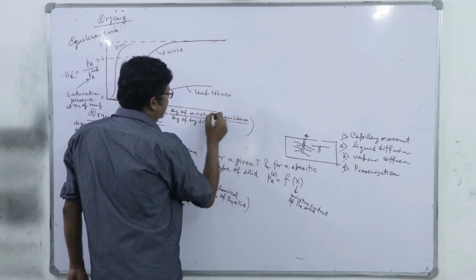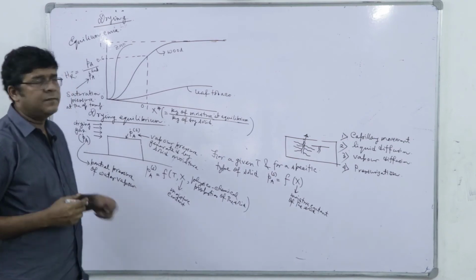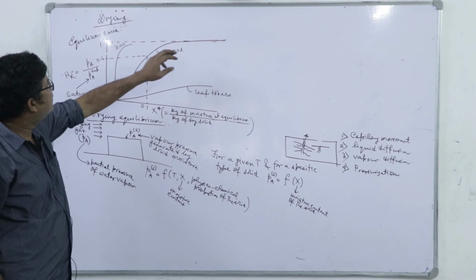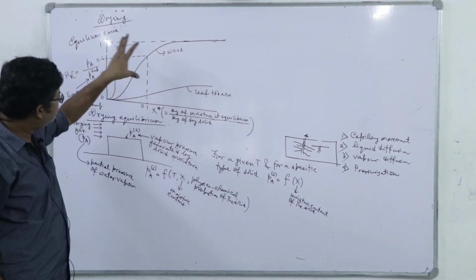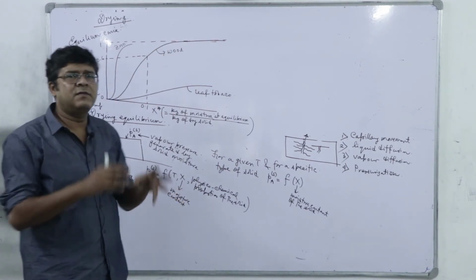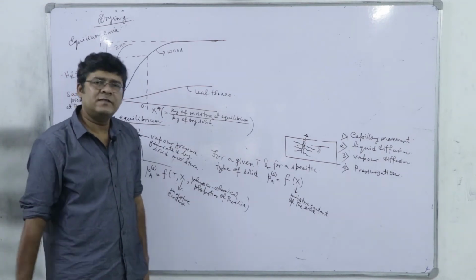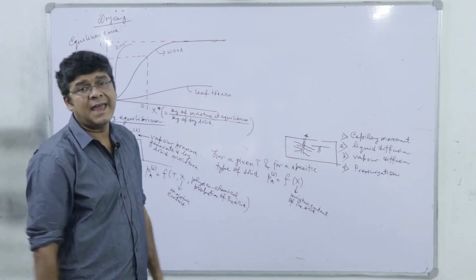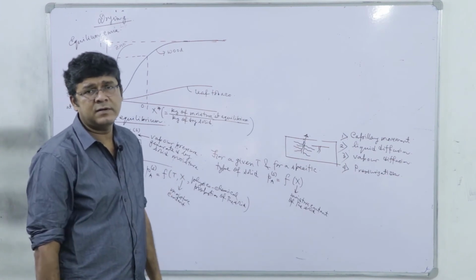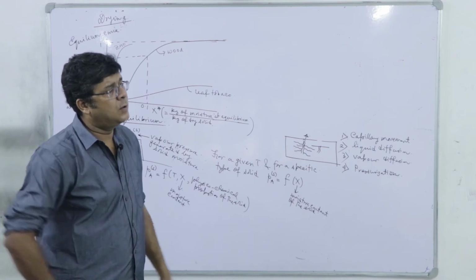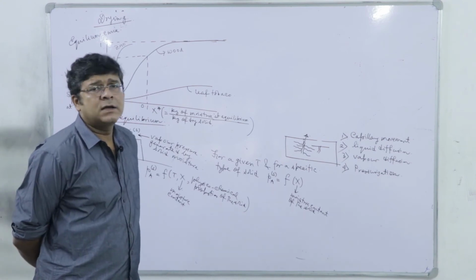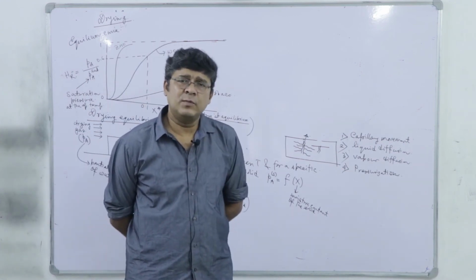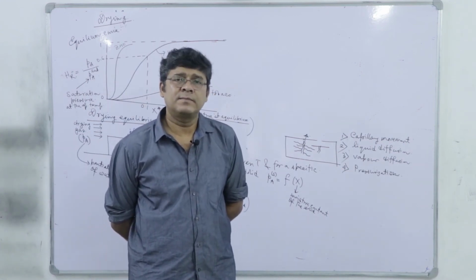So, how to generate this sort of curve? We will start working with wood. Wood will give a definite moisture content, we can change it, but let us fix it for the time being. Let us say the wood has a specific x value, that is the initial moisture content, and we expose the wood block to a flow of air with a given relative humidity, say 0.1.